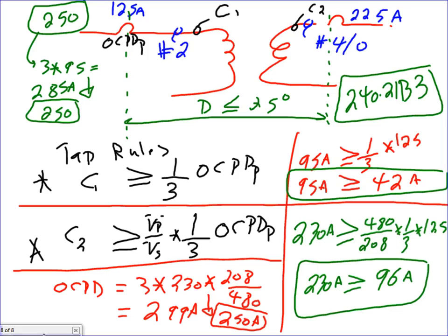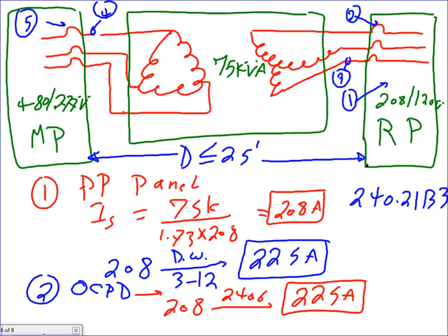Spencer, I'm sorry, the tap rules are funny and tricky, and they can save you a lot of money if you understand them. A lot of engineers don't even look at them. They just oversize things and call it a day. You just don't want to monkey around, so you oversize and call it a day. But they really can save you money if you understand them well. Especially that one with that transformer. Every industrial building is going to have this scenario, guaranteed. Because you have 480, 277, and you need 120 to power your receptacles. So how are you going to get to 120? You have to have a transformer that's 480 to 208.